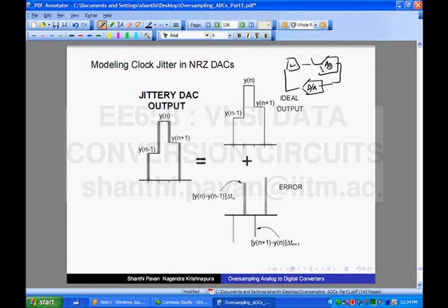This is a loop filter. All right, the output of the A to D is thankfully codes, okay? These codes are jumping around the nominal value, which is supposed to be the code corresponding to the input, correct? So to lead you to the answer, let's say I had a third order modulator, one with this out of band gain and the other one with a larger out of band gain. In which of these modulators will the output keep jumping more around the nominal? Pardon? So when the out of band gain is larger, the jumps in the outputs will be larger, correct?